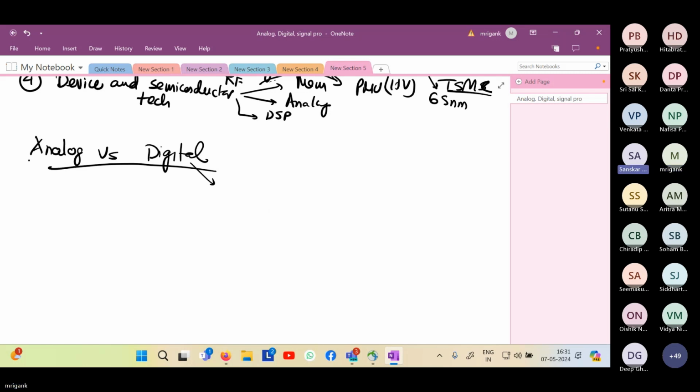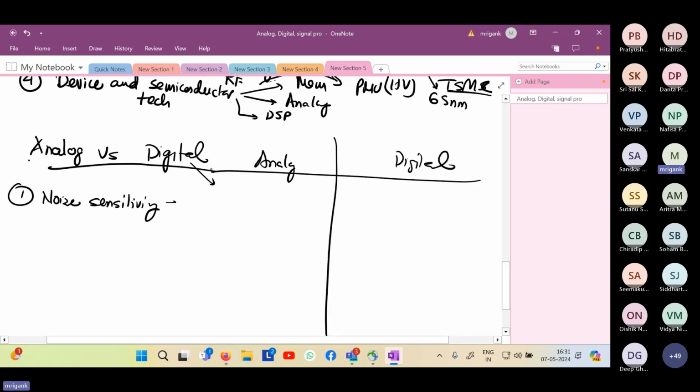They have a fixed high and a fixed low value. In an analog signal, when a signal comes in and if there is noise, the signal can have any value between 0 and say 5 volts, so the noise can affect it a lot. In a digital signal, low is defined as below 0.7 and a high should be above 3.5, so that can be maintained.